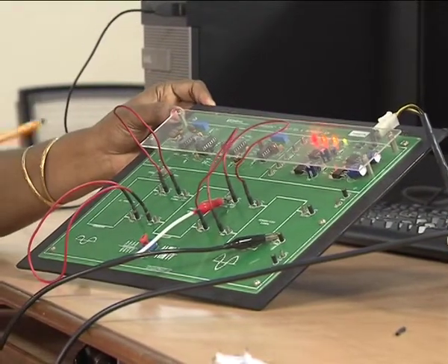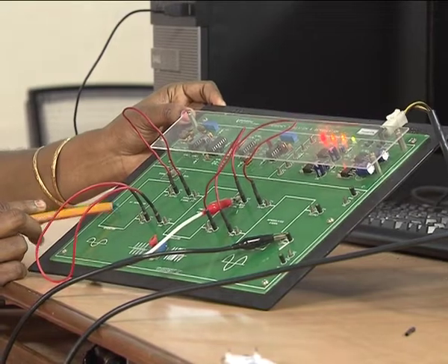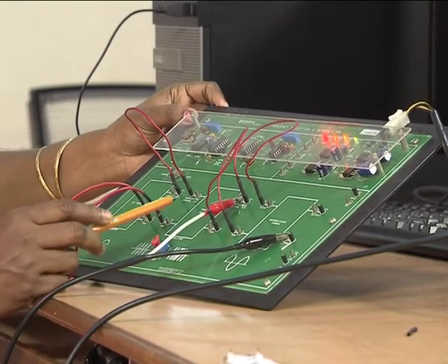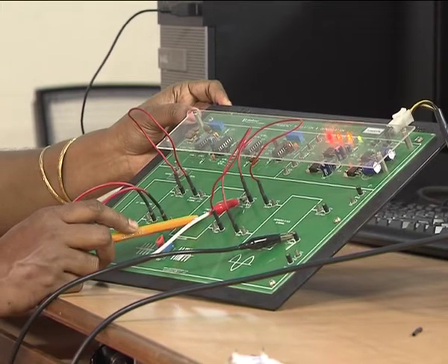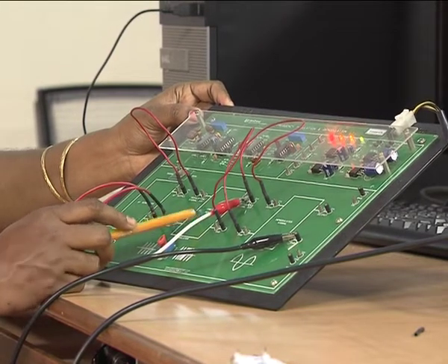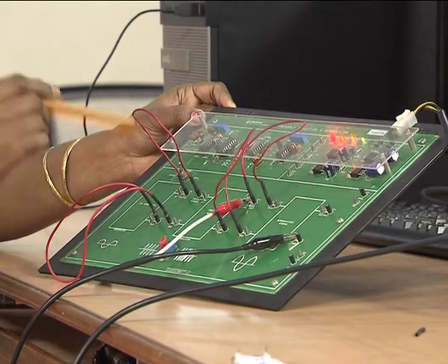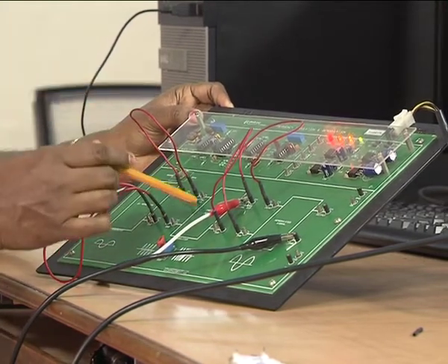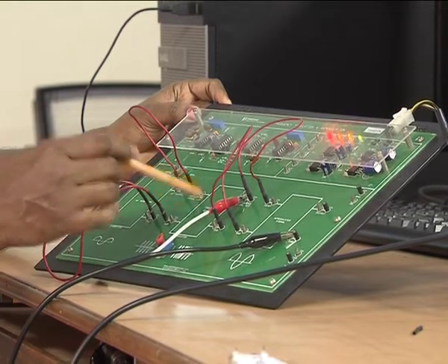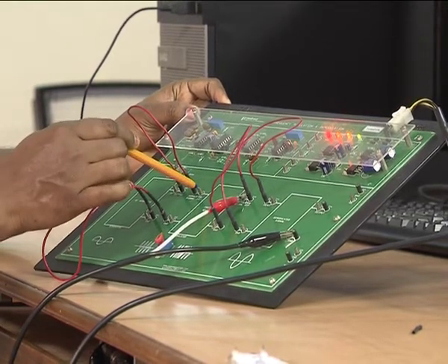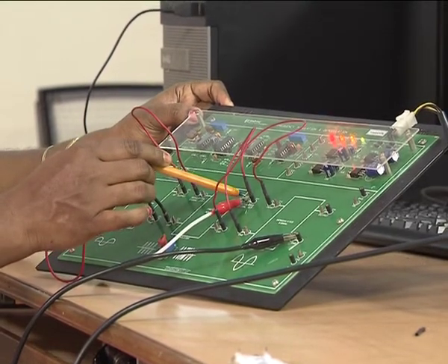In this kit we can see the input signal which is generated by the audio frequency generator, then a frequency deviator, which is nothing but the frequency modulator. This gets 2 inputs: one is from the audio frequency generator, that is your message signal, and the other is the carrier. The carrier is generated inside the kit itself and this is where we provide the message. After providing the message, we can see the modulated signal out of this pin.